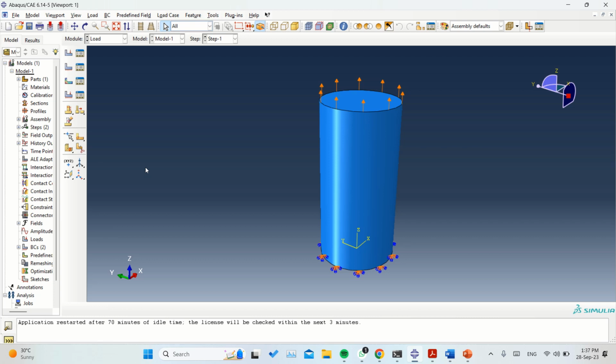Displacements and forces are connected with a stiffness matrix. F is equal to Ku. That is the equation of the stiffness method in the structural engineering subject. F means force is equal to K multiplied by U. Displacement and forces are directly proportional to each other with the involvement of K. K is a stiffness matrix.